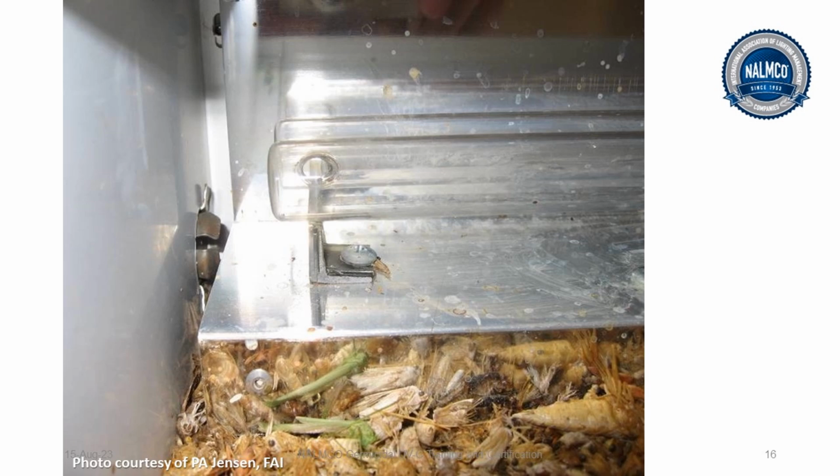This is really why there's a lot of loss. And after the proper cleaning, which probably took them about an hour because the bug residuals were so dried on, it was very difficult to clean the reflector and the lamp. Afterwards, they were able to get up to about 14 or 15 microwatts per square centimeter. So it's still a significant drop, and the lamp should be changed. But this is why you take a witness point after installation and whenever you do your periodic maintenance.